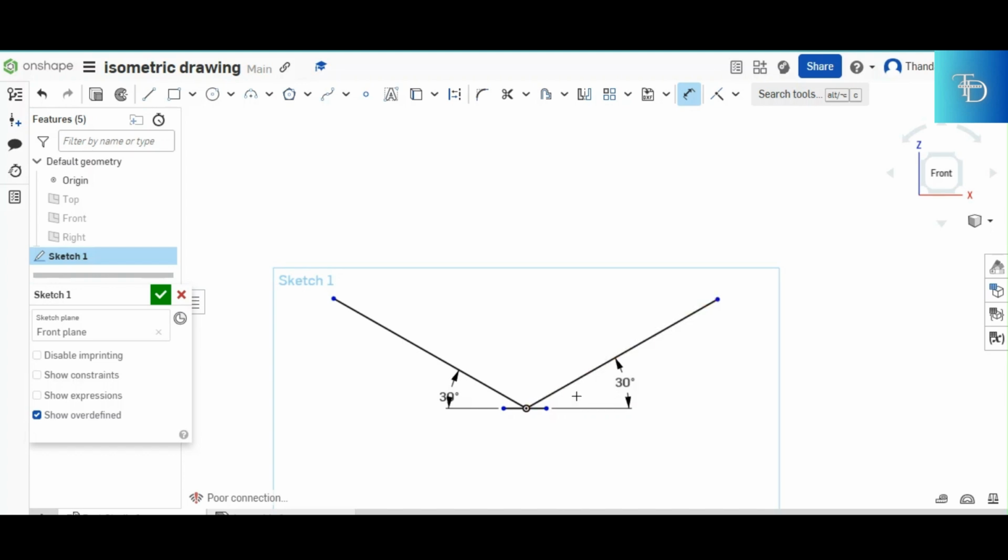So now coming back to your cube construction, you already know that since this thing is in first angle orthographic projection, it means that your front view is going to be on this side, and then on this side it's going to be your left view. And then the next step that you do is you draw a straight line from that point P, which is the lowest point, going up without measuring anything.